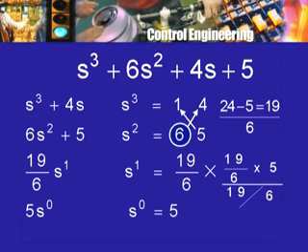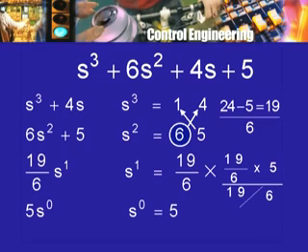And that is right, because in the s to the 1 row, what is the polynomial? It is a polynomial whose highest power is s to the 1, and is there an odd polynomial? Is there going to be any other term? No, because s is the smallest odd power of s that you can think of. So, that is it. If you want, I can put a dash here that there is no number to be filled in here. So, my next row calculations are over, but my table calculations are not over because I have the power s to the 1.